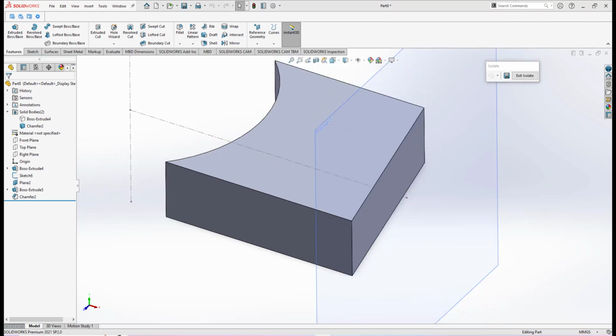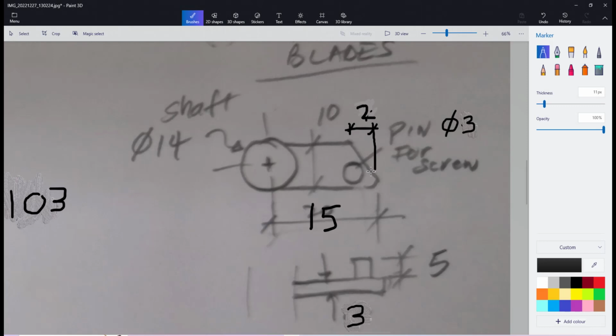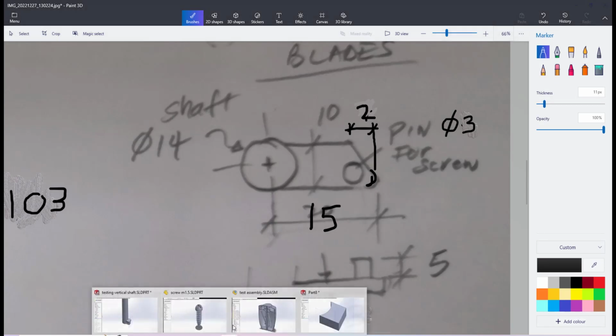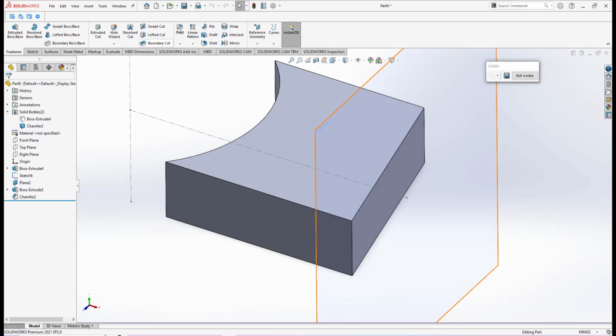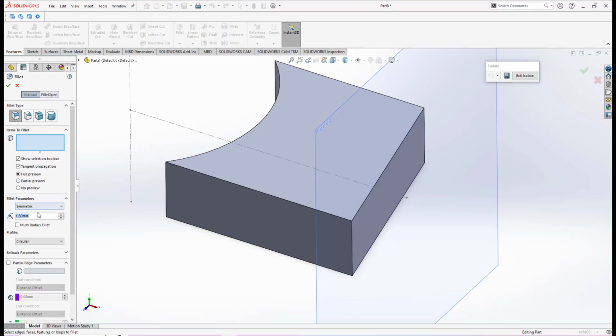so I can make a detailed modeling onto this arm. Alright, if you look in this photo, the arm at the end here, they kind of like have a curve here. So I will do fillet by radius of 2 at this edge.